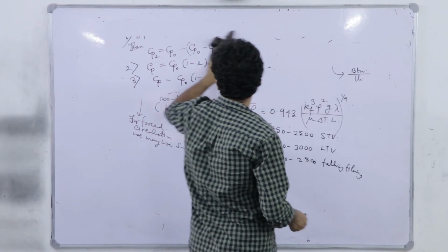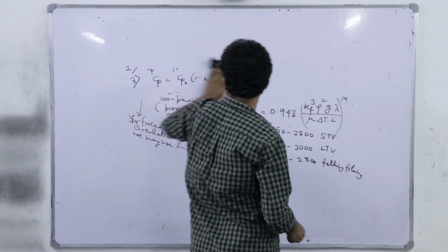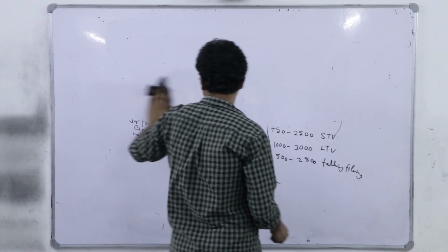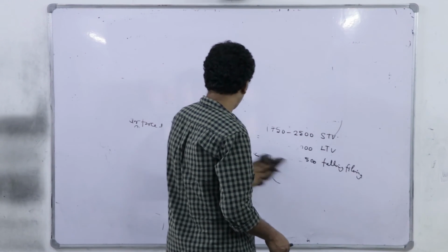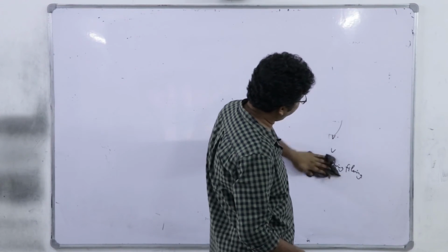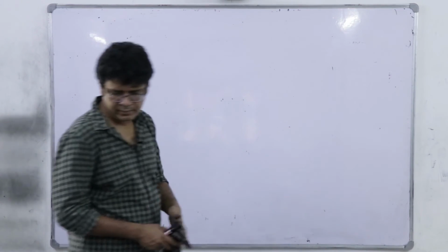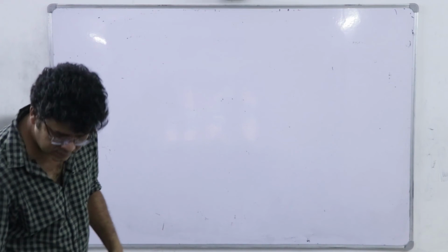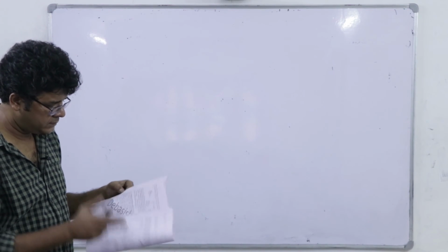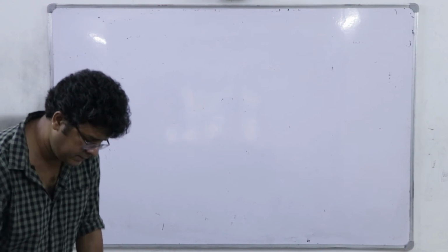Next let us discuss the material balance, energy balance and the capacity equation of a single effect evaporator, wherefrom we can solve for its heat transfer area, right.